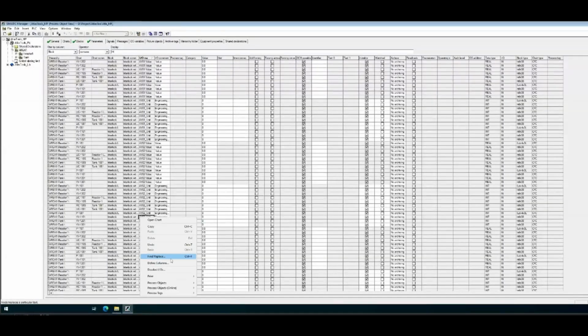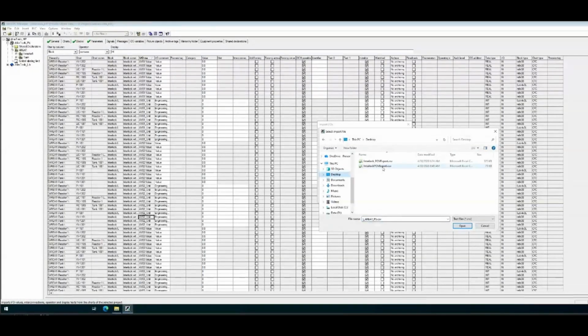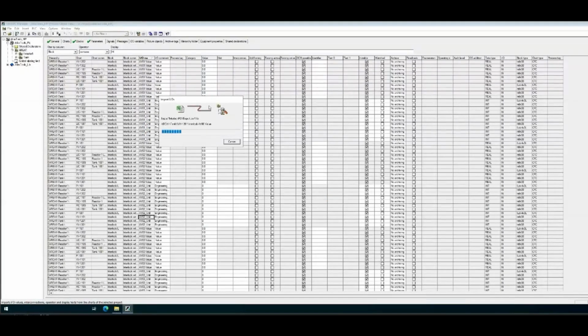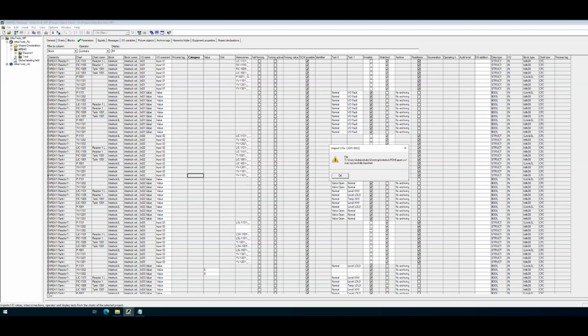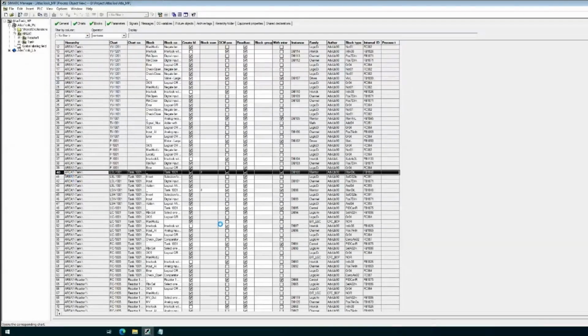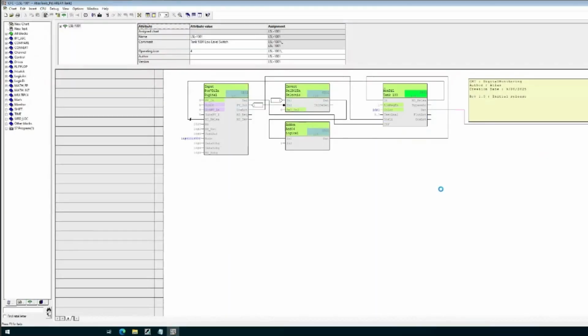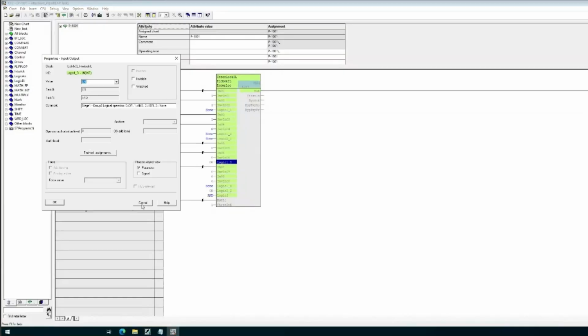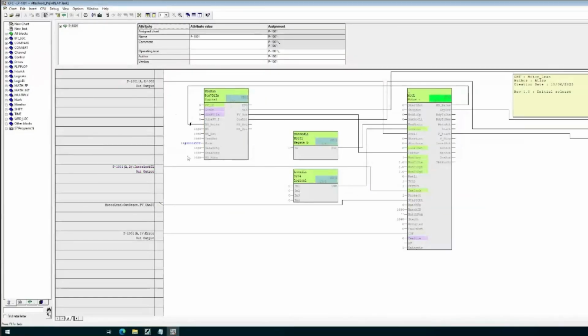Now that our Interlock Import Tool has taken the interlocks on the matrix and inserted them on that process object view export, the next step is to re-import that same process object view back into the project. Now that we have successfully imported the process object view, we can now see that the interlocks and their interconnections have been successfully imported, and we can even go and open up charts and see what those look like.